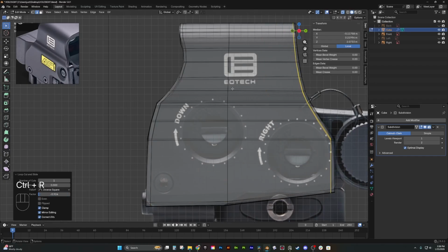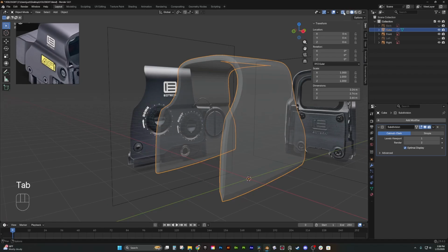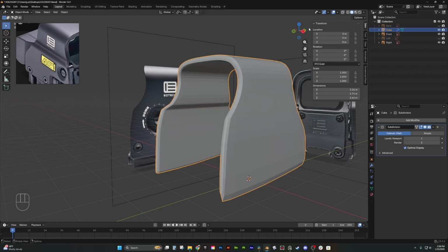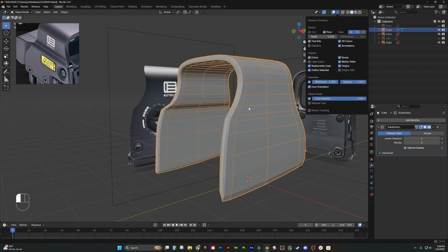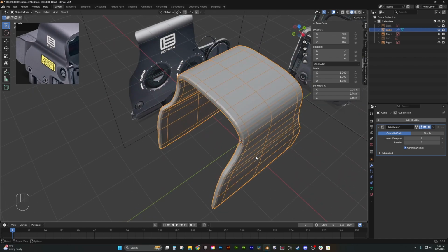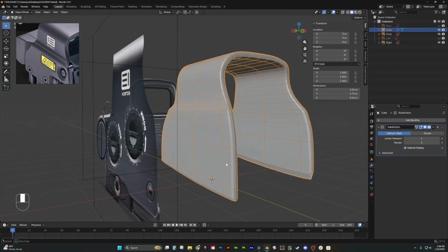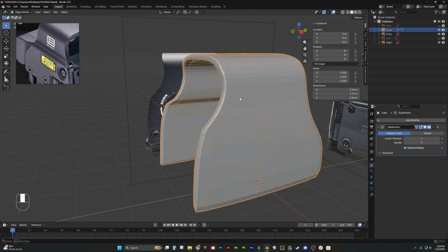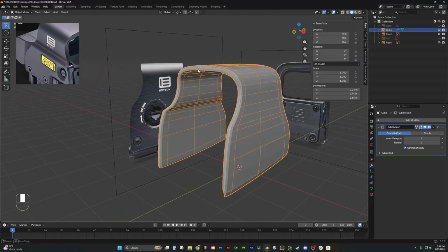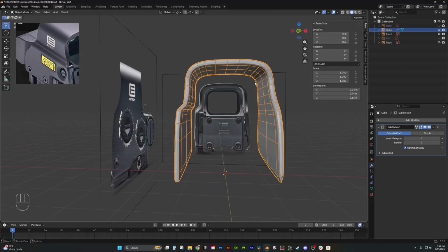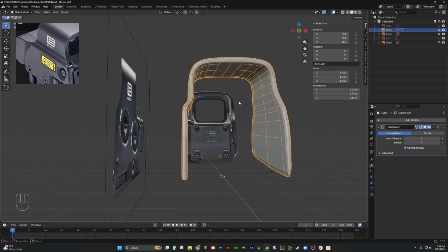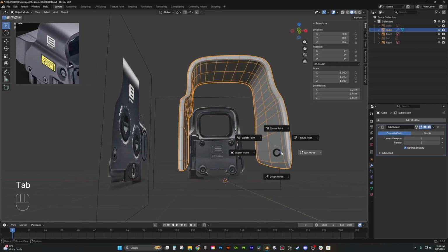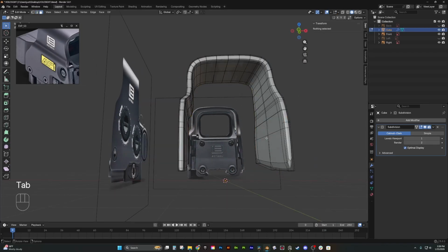I may be underestimating the difficulty of what is called polygon flow, but if I go to the wireframe, notice that they are all following a single direction, and it allows me to add control loops without disturbing the model. It allows me to extrude pieces very cleanly. So I knew that it would be pretty difficult when we didn't have this interface to try to rebuild it with certain other methods.